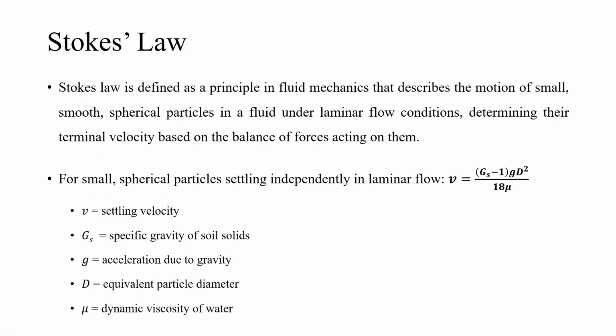So let's understand Stokes' law, which is the foundation of this hydrometer test. Stokes' law is a principle in fluid mechanics that describes the motion of a small, smooth, spherical particle falling through a fluid under laminar flow condition. It gives the terminal velocity of the particle based on the balance of forces acting on it, namely gravitational force, buoyant force, and viscous drag force.